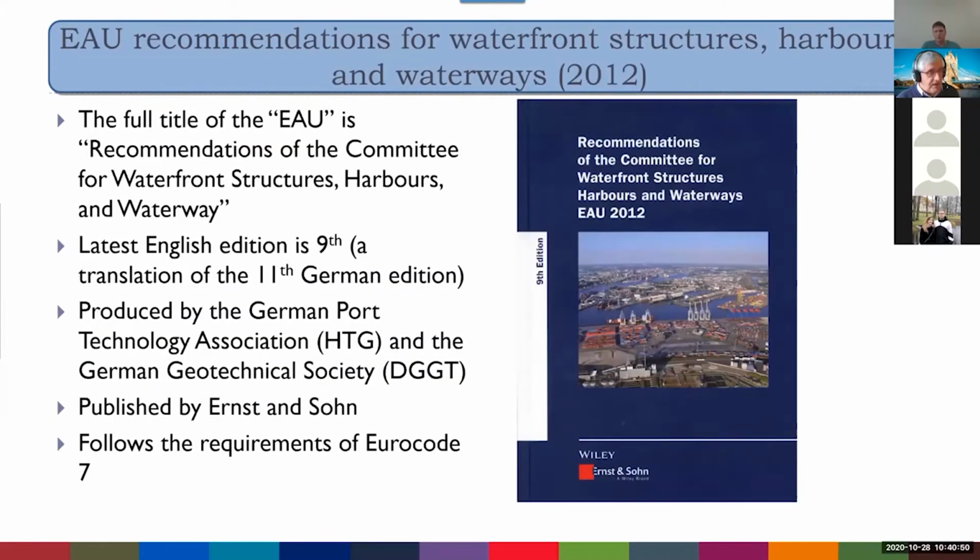And another document I would strongly recommend is the German document, commonly known as the EAU, which is the recommendation of the Committee for Waterfront Structures, Harbours and Waterways. The German edition is on its 11th version. There's an English translation, which is the 9th edition. And the fact that we're on a 9th English translation tells you how valuable this document is. It's produced by the Port Technology Association, the German Geotechnical Society. It's got a lot of very, very useful information in it. And if I'm doing a retaining wall design, I'm using this equally with the CIRIA guide from the UK and the British Standard. I regard all of these documents as very valuable, no matter which country you're working in.